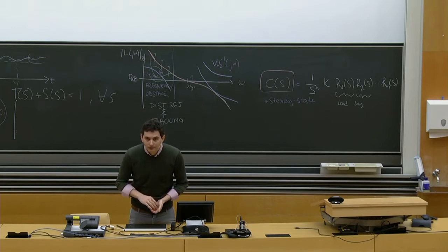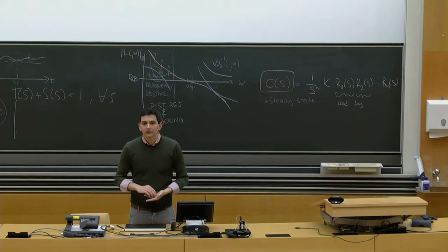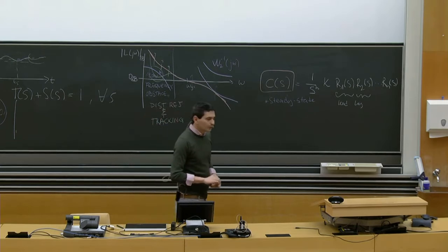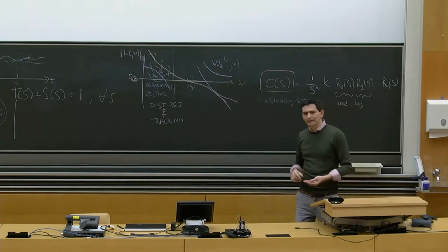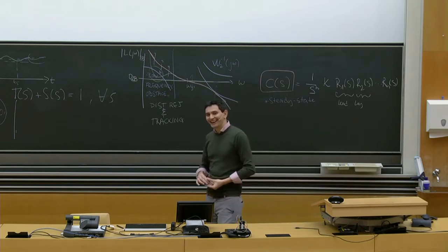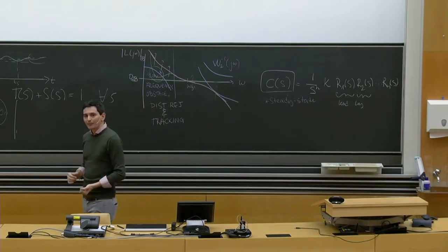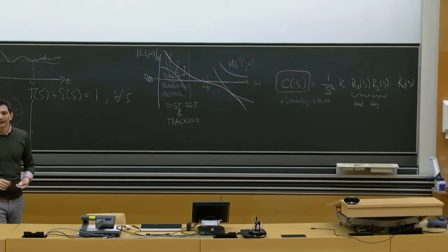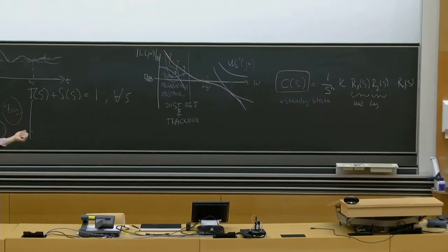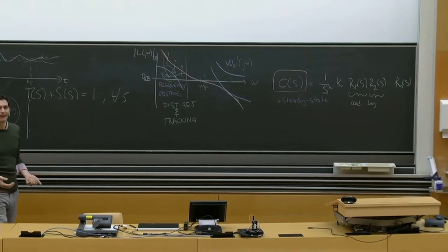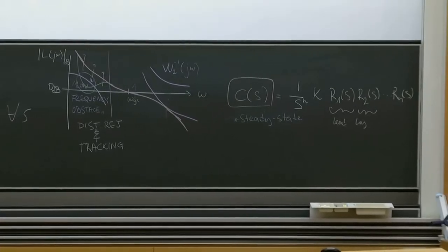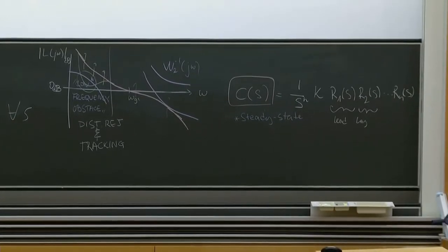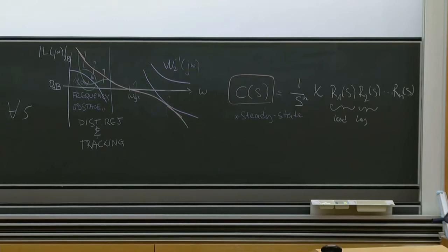We realize that with lead or lag functions and integrators. But does a PID loop exactly do this? Yeah, so a PID loop can be rewritten as a lead lag compensator. And there was one slide on this last lesson. Maybe it was the last slide of the class, but you can literally rewrite a PID compensator as a lead and lag. And it's kind of an extreme lead lag. You will see that if you check the math and you just factor things in the right way, it would be lead and lag networks that have various extreme choices of the poles and zeros.